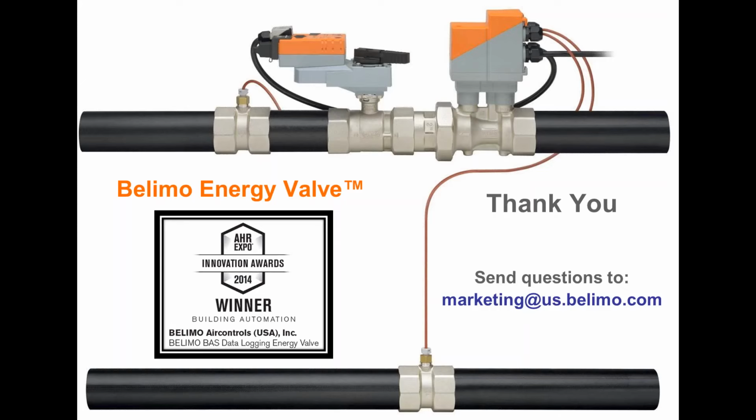Because frankly, if I get a huge delta T at my coil, but I'm hurting my chiller while I'm doing it, it's not really an energy savings measure, because my pump costs will be less, but my chiller cost is going to go back up if I have too much inefficiency because the delta T is too high. But again, I would reach out to your chiller manufacturer rep to have that discussion.